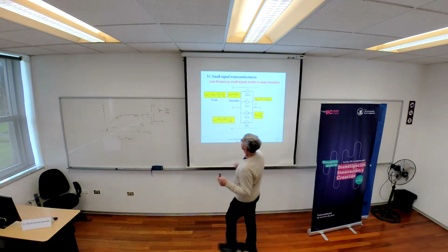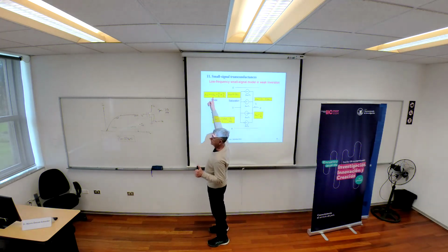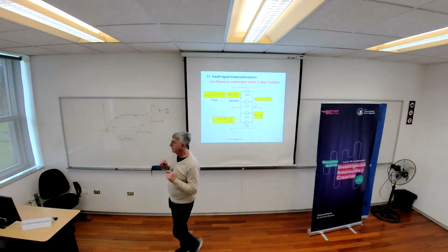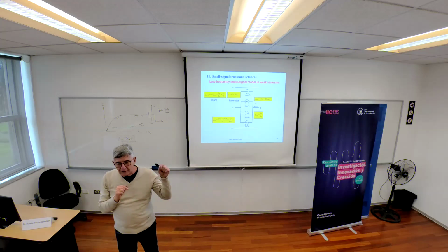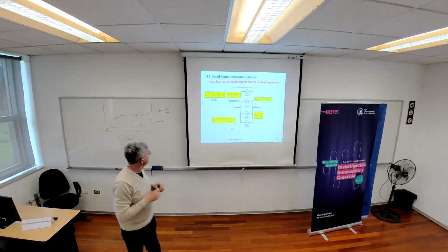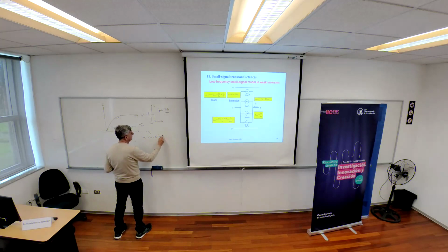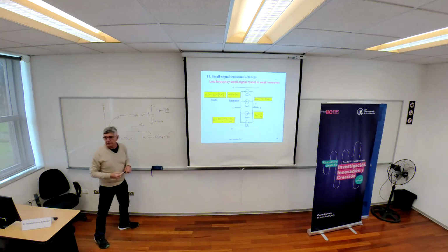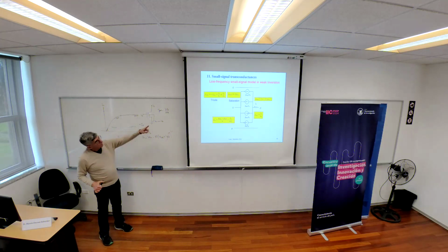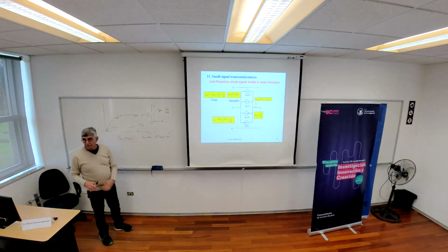This is a consequence of the exponential dependence of the drain current on the threshold voltage, because the threshold voltage is dependent on the DIBL factor. We have another term here, but in this case, this is 0. The VSB equals 0. So this result is just a consequence of this dependence of the threshold voltage on the drain to bulk.